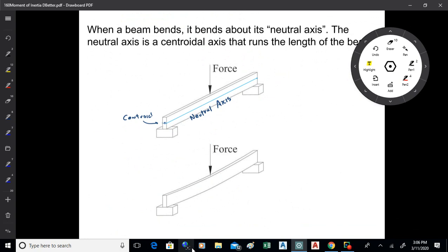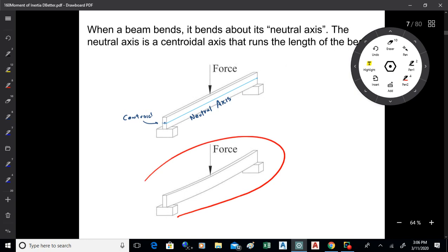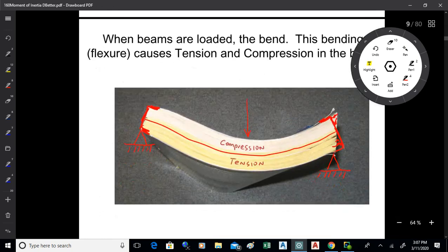So you look at the cross-section of the beam and calculate the moment of inertia about what's called the neutral axis, which runs through the centroid on the cross-section of the beam. And that number gives you some indication how much stress will build up in the beam as it flexes, as you're seeing right there, downward, okay? So that's what this number is. It's a bit abstract, it's not like a centroid where you can point at a location on a beam and say there's the centroid. It's more abstract.